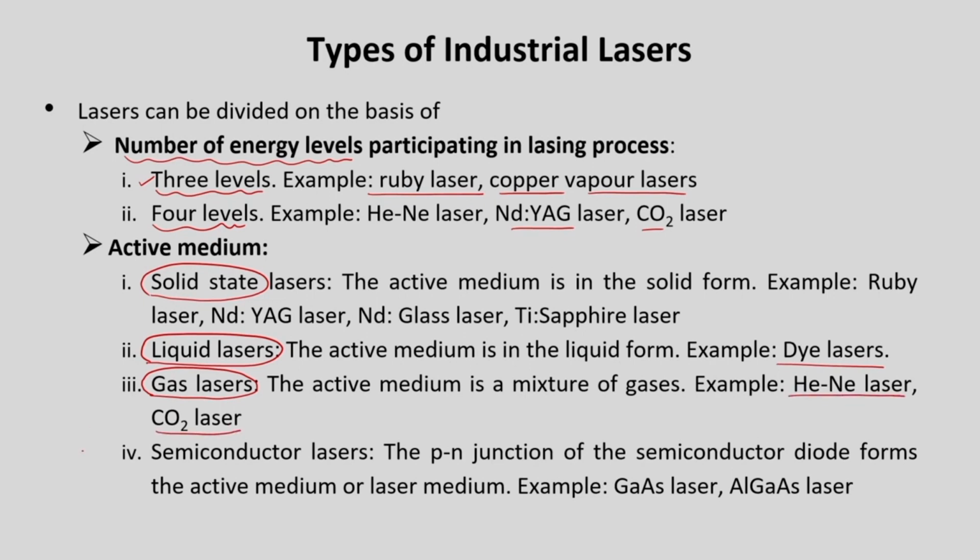We will be looking at all the lasers when we discuss the application of these lasers for manufacturing operations. CO2 lasers or Nd:YAG lasers are very widely used in material processing. We will look at them in detail when we move ahead. Excimer lasers and even diode lasers are also being used in manufacturing operations.